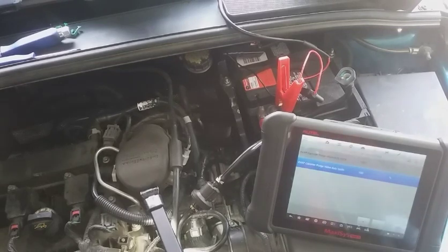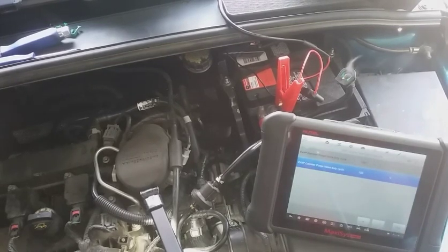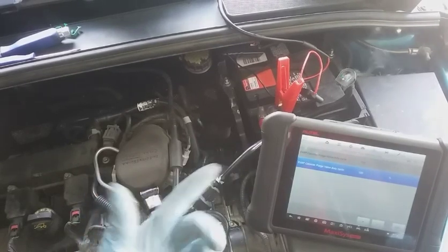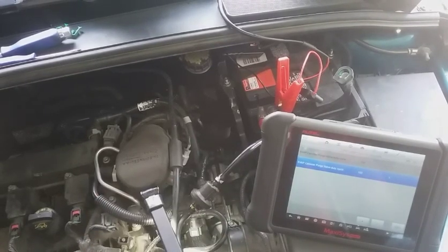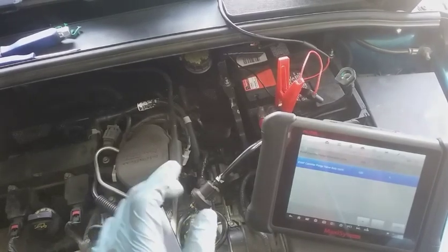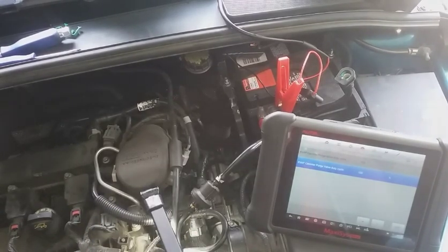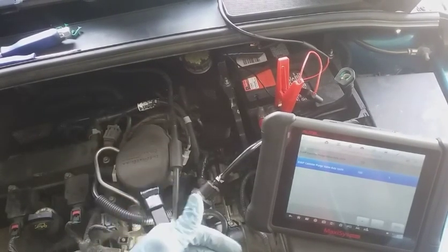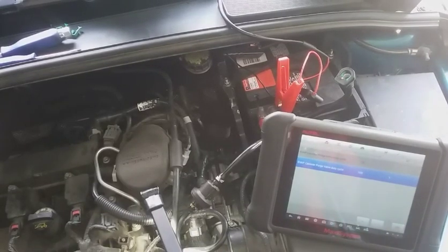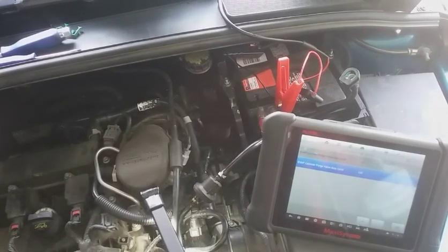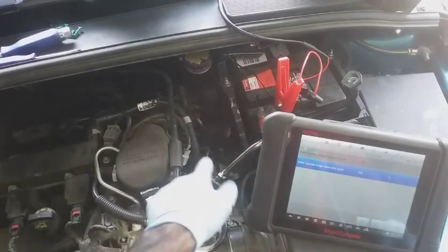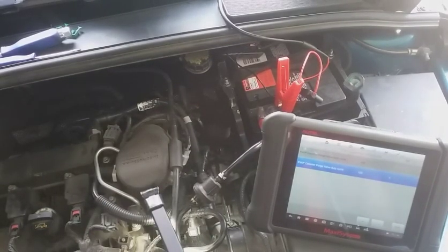But even so, how can someone test this if they didn't have this scan tool? I do recommend that everyone, I guess the mechanics out there, get a bidirectional scan tool. It's very necessary for these issues. What you could do is drive the vehicle, and after you achieve a certain speed or a certain temperature, the computer is going to command this evap purge solenoid to operate.